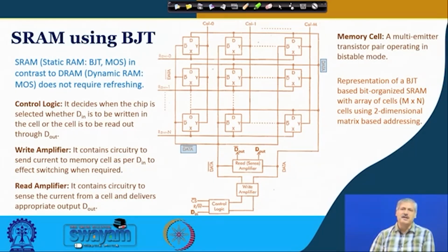In DRAM the number of parts required is less. Here the number of transistors and other circuit elements will be a little bit more. So, in DRAM the packing density will be more, but SRAM will be faster, and refreshing is not required. So, these advantages are there. More of DRAM we shall see later. Today we discuss this static RAM memory unit, and more specifically the memory cells.